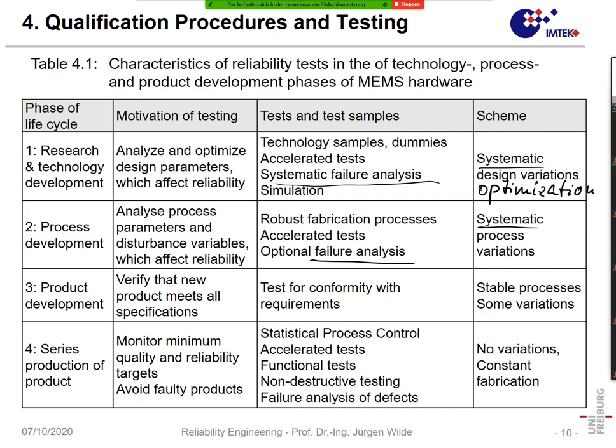When we do a product development, normally we design tests which are similar to the phases 1 and 2, but how long do we test then in the product development? So here we indeed say we want to have it for a lifetime of, let's say, 3,000 cycles, and we test for 3,000 cycles or even for 4,000, and we require that there is no failure.